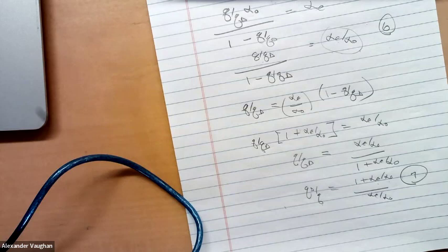I think that's all I want to tell you about divergence. I had some pre-class notes. I want to make sure I hit on all the points I didn't think I did. Professor, will the divergence dynamic pressure always be less than a flutter dynamic pressure? No, no, no. It can go either way.